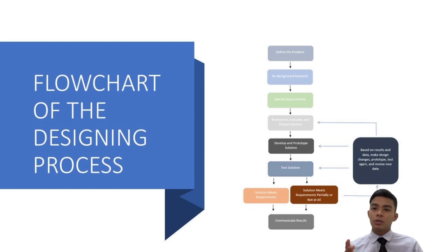The bearing should have low friction, and can be optimized for low vibration, which enables high rotational speed. It also should support radial and axial force to rotate freely. The material type of the rig also should be impact resistant and high strength to sustain its position. Two different diameters of rod were used in the study, which are 9.5mm and 6mm. The 9.5mm will be the stand and the 6mm will be the hang. The height of the rod is 225 cm and the hanging rod is 13 cm.